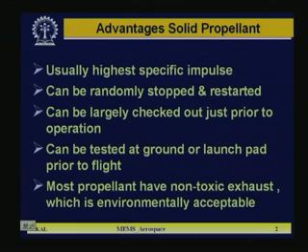Now the advantages of liquid, sorry, the heading says solid, it should be liquid. Advantages of liquid propellant: it usually has the highest specific impulse, can be randomly stopped and restarted, which cannot be done in the case of solid, can be largely checked out just prior to operation, and can be tested at ground or launch pad prior to flight. Most propellants have non-toxic exhaust, which is environmentally acceptable. These are the plus points in the case of liquid propellant.